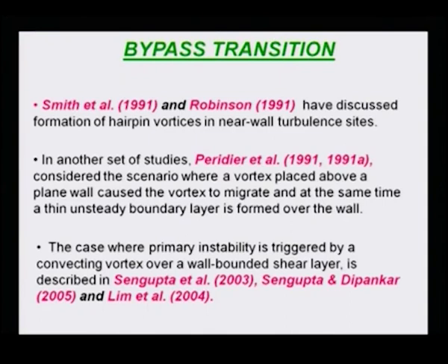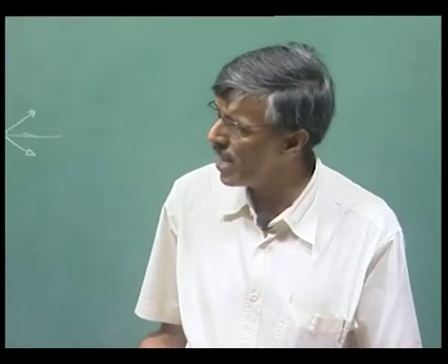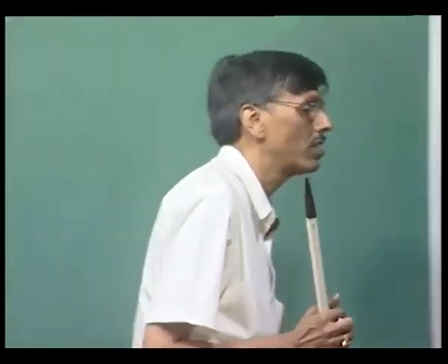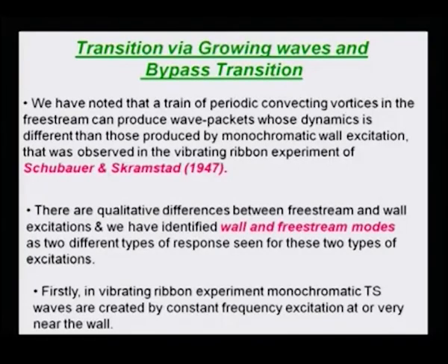And the second paper in 2005 that we are looking at here, we studied the instability of a flow over a swept back wing on the leading edge. This is what is called a leading edge contamination problem. That's what we have to talk about a great deal too.